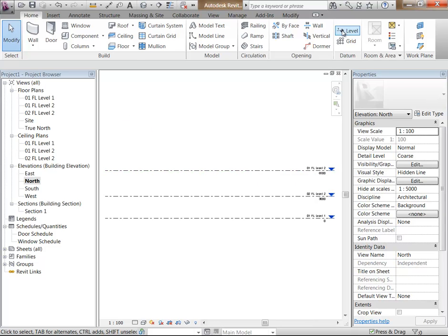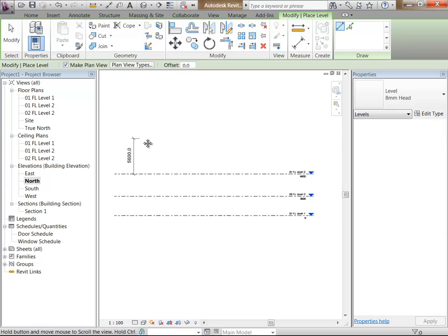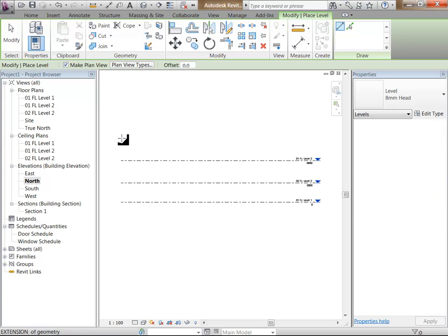So when you draw a level, that's why I always say generally left to right, if your tags are already on the right, because then it puts the tag on that side. And it does it for all of your views. It lines them up. If I go right to left, the tag goes on the wrong end.